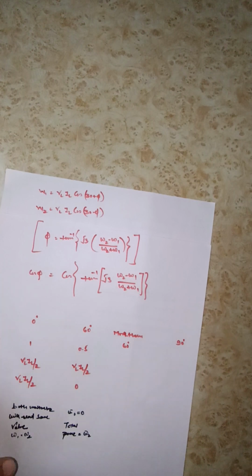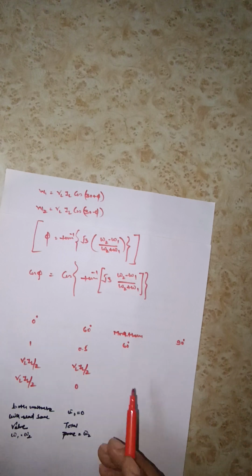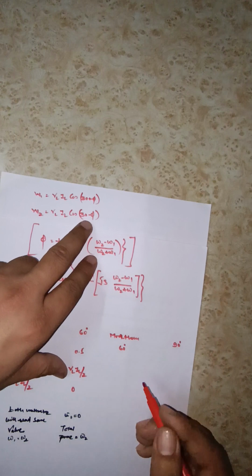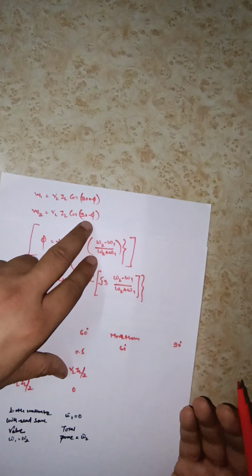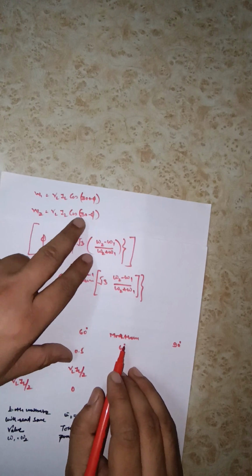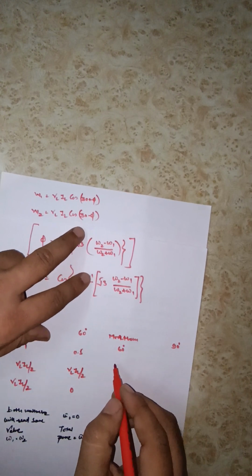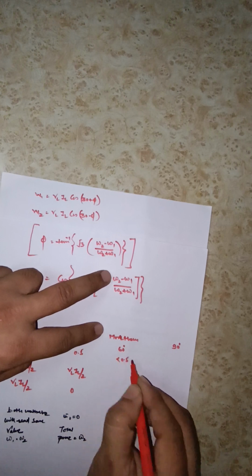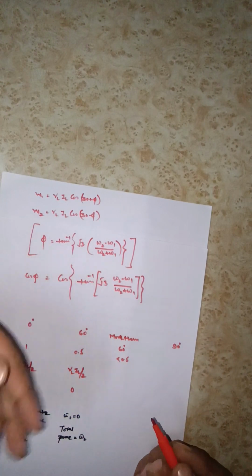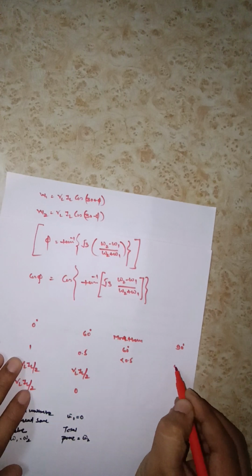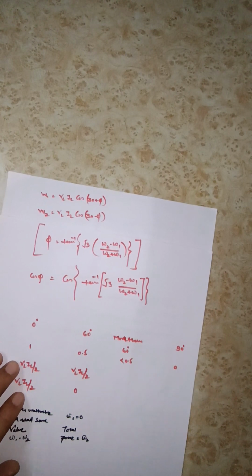Okay. Now next is when it is more than 60 degree. Again, let us take some example like 75, 80, something like that, more than 60 degree. Then W2 will again provide you a positive value, and what will be the power factor? It will be less than 0.5, because as the angle increases, the cos value will reduce, and at 90 degree the value will be 0.